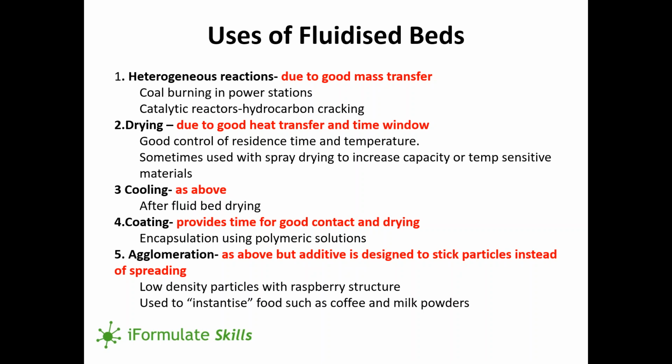And this process is used to grow particle size, as Jim mentioned, in fluidized beds, and is used to instantize food products such as coffee and milk powders by growing the particles and making them slower to wet and dissolve. So it allows the particles to be dispersed in the liquid before they dissolve.